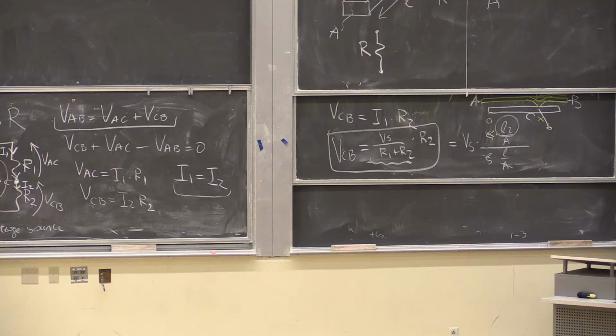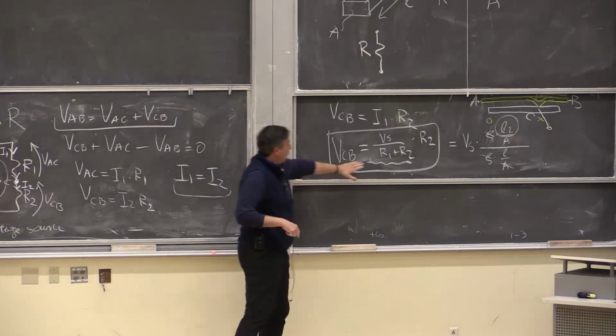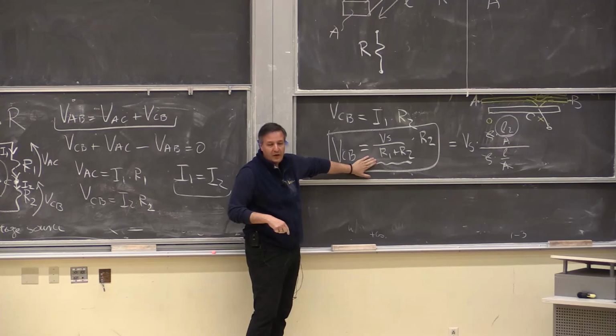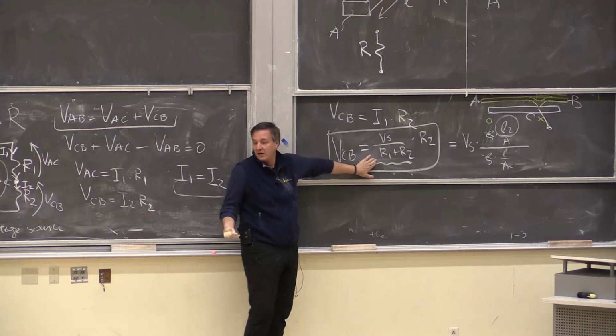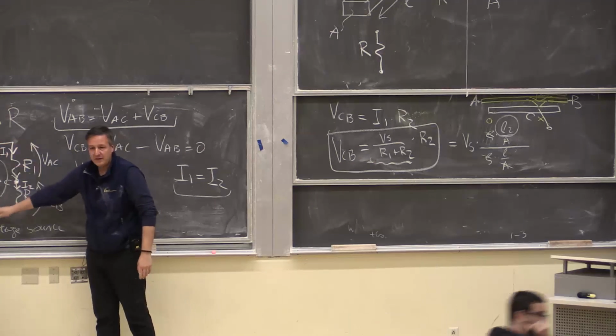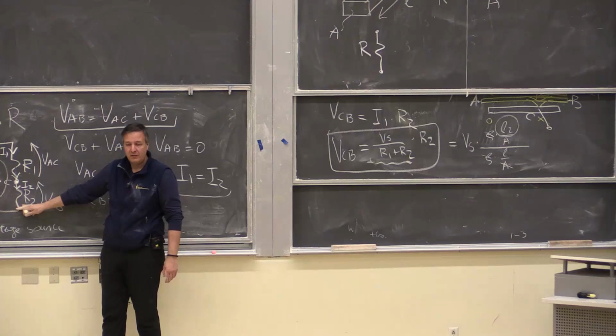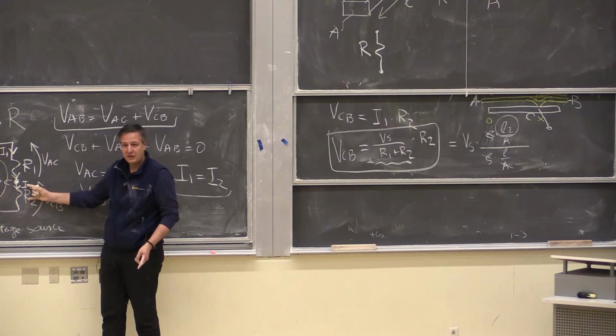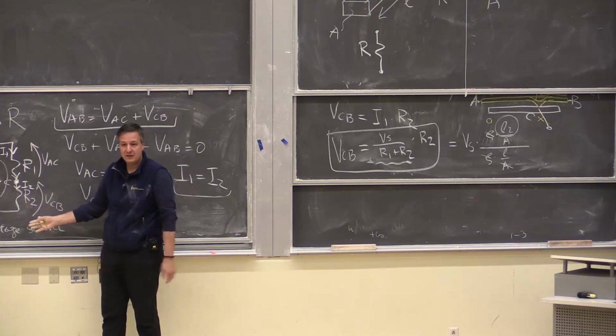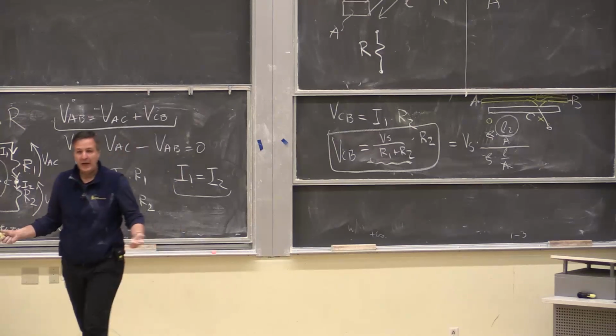All I need now is some magical circuit to read that voltage and process it. Let's say you can make a little instrument where a note is proportional to the voltage you're getting along the wire you're pressing, right? Another key thing that we've done here is we have defined an operator. An operator is called a voltage divider. And this is the first operator in circuits that you're going to be using. I take the supply and I divide this supply voltage across this resistor. That is proportional to the magnitude of this resistor over the total resistance that this voltage sees. Okay? So next operator, next class.